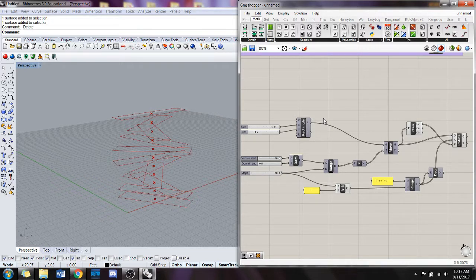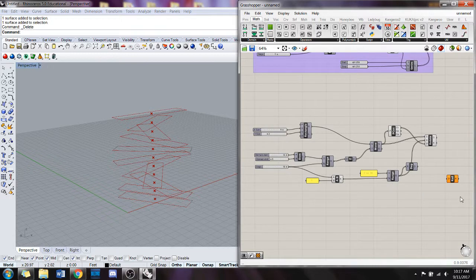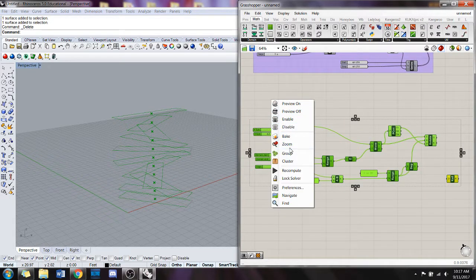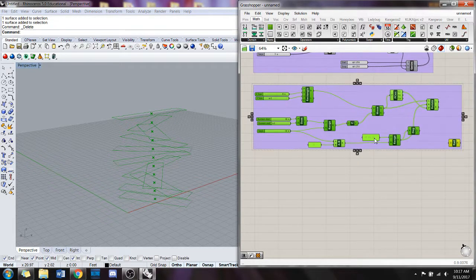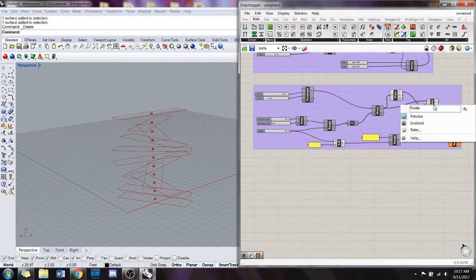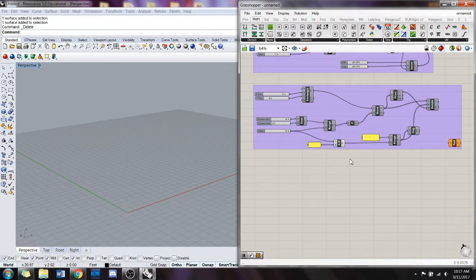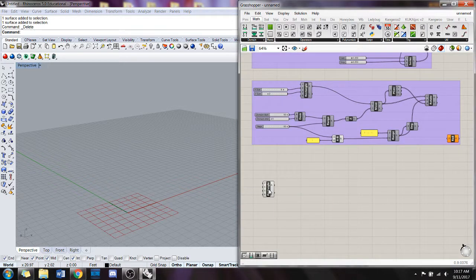The last thing we're going to talk about before we sign off really fast is the region difference component. And that's going to effectively act as a Boolean difference that will let you either cut away or break into a different set of shapes where they overlap. So we'll use a rectangle. Build your favorite rectangle.